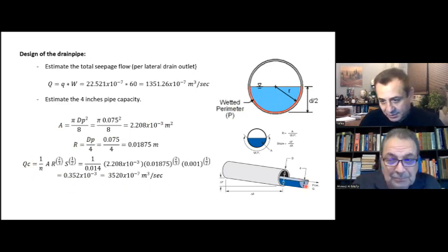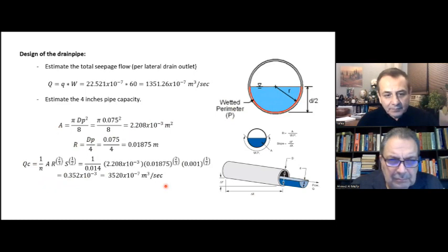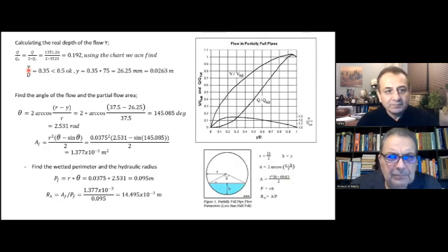As you see here, it's half the flow. But really what happened in our design, it's not necessarily that we're going to get the flow up to half. Should be less or equal half. So how do we know that? We get this QC, and the Q full, if you remember, is 2 times this. So we need the Q full.